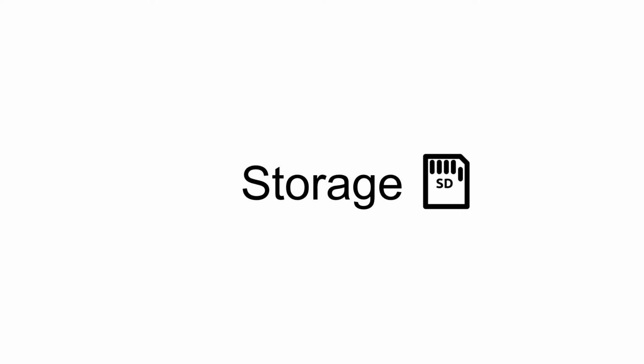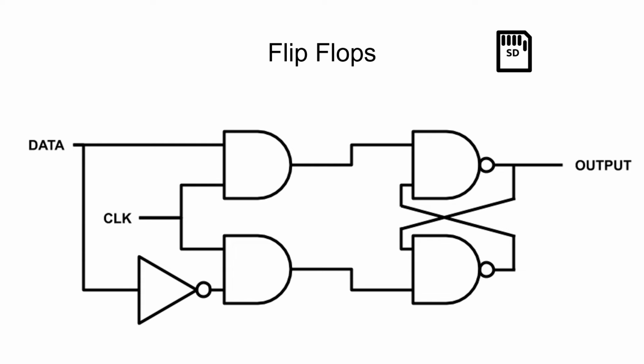Storage within an FPGA is generally handled in one of three ways. The first and most commonly used form of storage in FPGAs is the flip-flop. Flip-flops, also known as registers in FPGAs, can be used to store relatively small amounts of data that is immediately accessible to custom logic written in an FPGA. While they can be defined to be addressable, they are not inherently addressable.